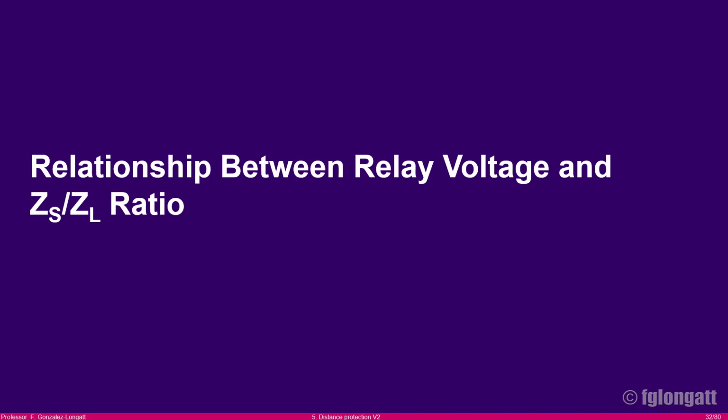We prefer the use of distance protection because the fundamental of distance protection is using the ratio between voltage and current. And that is extremely helpful because it avoids some of the drawbacks coming from overcurrent and grading. But another thing that is extremely important is that the distance relay also has some limitations.